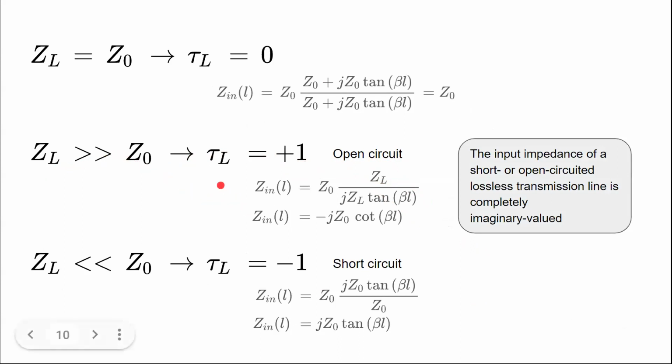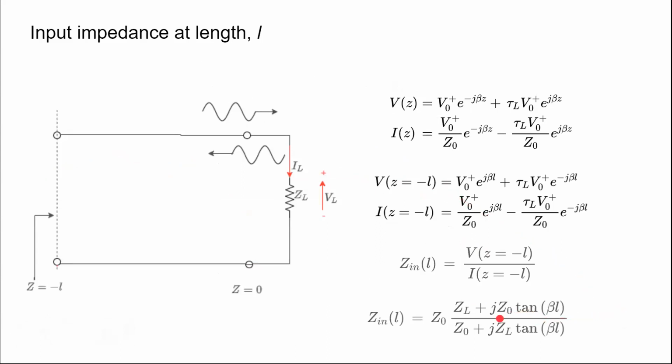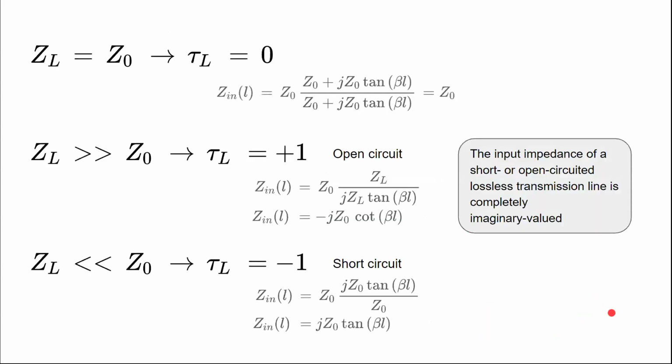In order for us to calculate that scenario, we need to do a trick. We need to divide each term by ZL, and then substitute infinity after dividing each term by ZL. I hope you can understand. You can't just substitute infinity into both numerator and denominator and write infinity over infinity. It is not a defined term in mathematics. In order to make it defined, we need to divide each term by ZL. And then you can substitute ZL equals infinity. Once you have substituted that, you can make some terms 0, and you are left with this term, right?